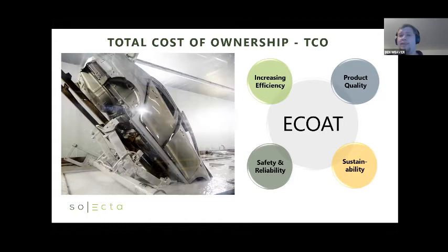The membranes themselves can go up to a max temperature of about 122 degrees Fahrenheit, 50 degrees C, and a max pressure of about 70 psi for the elements themselves. And for pH, we can clean anywhere from 2 to 11.5 on the pH scale. In operation, the membranes can handle about 4 to 10 in consistent operation.